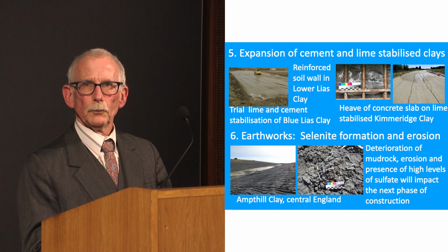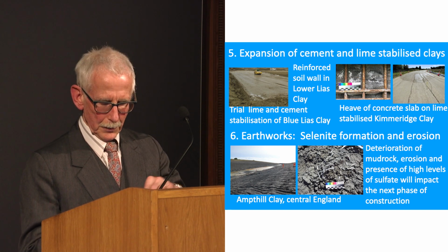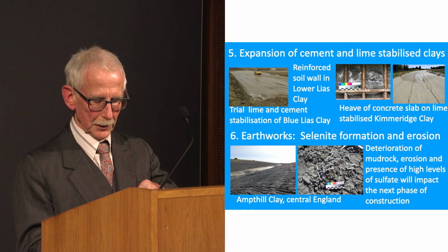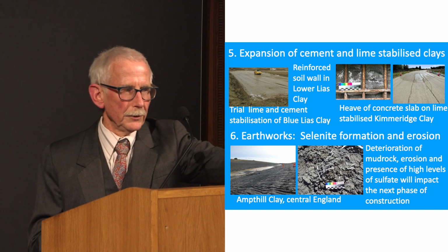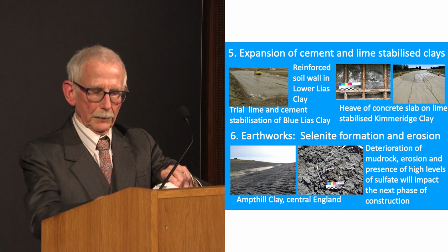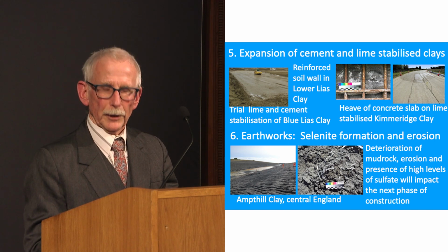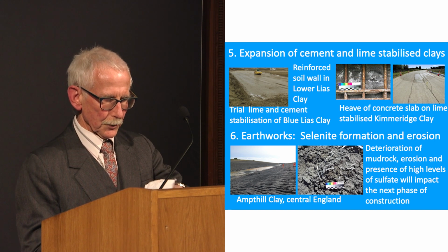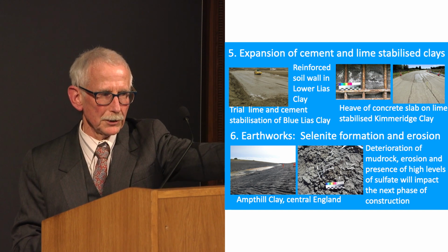The reinforced soil wall at the top centre has deteriorated badly. It's built out of lower lias clay, and that has been seriously impacted by the pyrite in the clay, which is corroding the reinforcement and also leading to degradation of the clay.